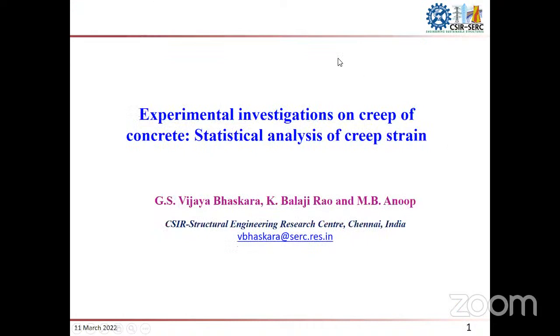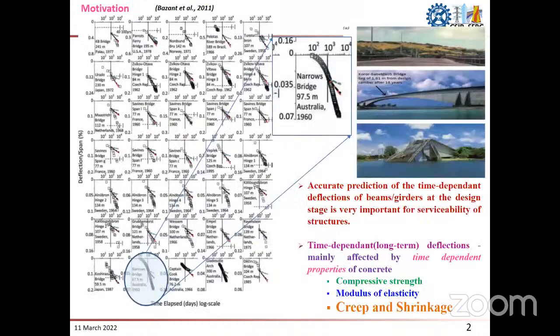My topic is on creep of concrete. Here we try to understand the creep mechanisms of concrete, how creep strains evolve with time, and using the retardation spectra concept and some statistical analysis, how creep strains manifest at different time scales.